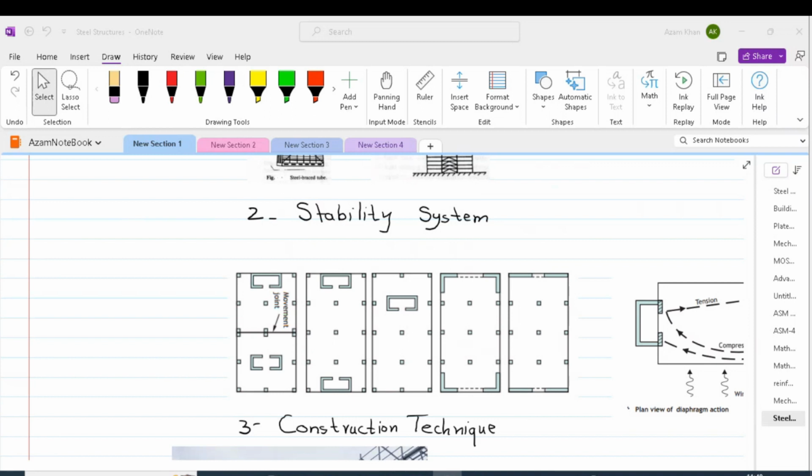Similarly, a building might have shear walls responsible for resisting the lateral load caused by wind or earthquakes. These also provide lateral stability to structures. We can also have moment resisting frames to resist lateral loads. These frames provide resistance by allowing controlled flexing of the building structure. The bracing system, shear walls, and moment resisting frames are all examples of lateral stability systems.